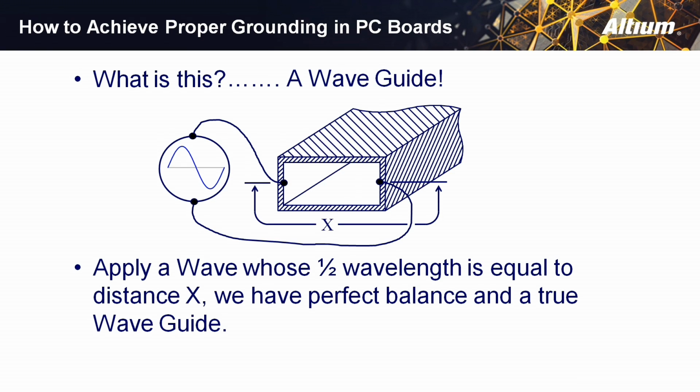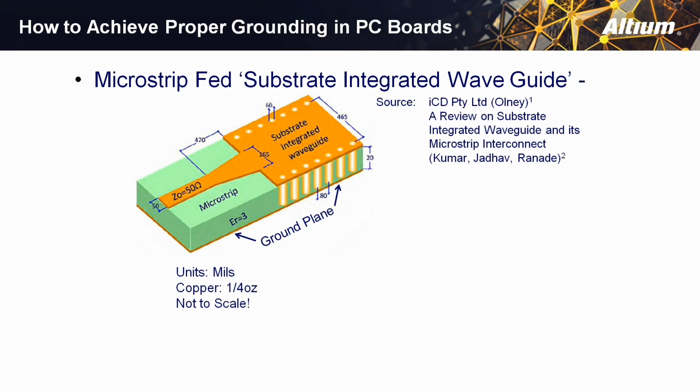The beauty of a waveguide of this type is that it's designed to transmit one frequency of energy only. Any stray energy that's attached to that will basically get shorted to the metal and won't appear as a standing wave in the tube.